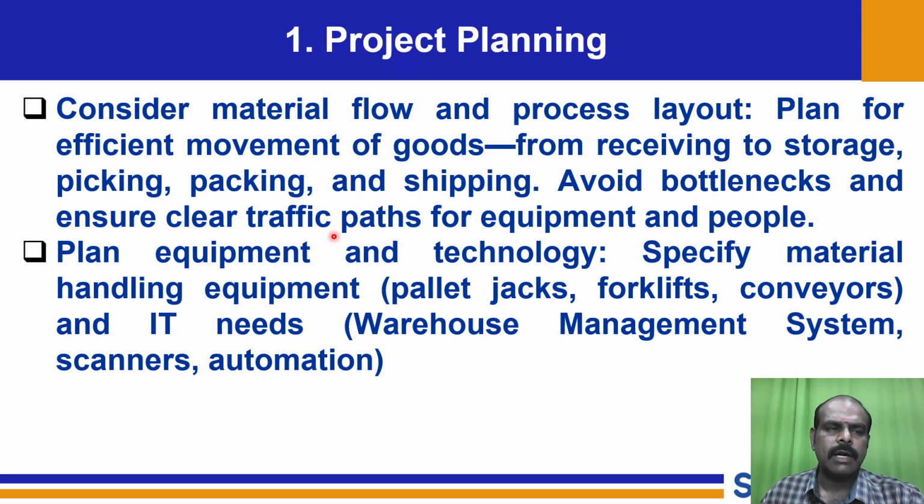So we should clearly go ahead with one important activity, that is how are we going to handle the material? What are the different types of material handling we are going with? Initially we might be using some sort of pallets or forklifts or conveyors, or in some cases some lower level activity, say for example, some manual based activity, say carousels, manual lifting. Then later on we might change to forklifts and in turn to AGV and AMR.